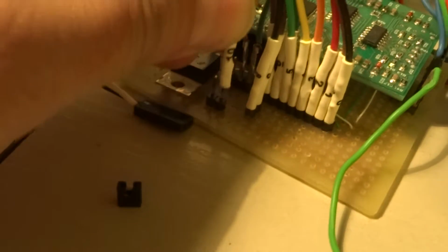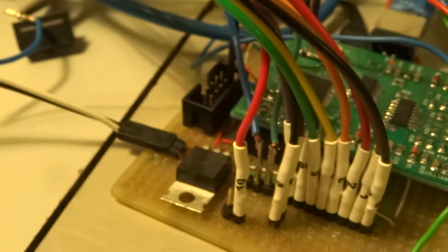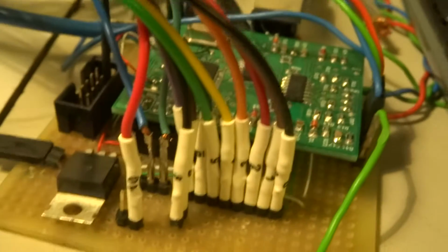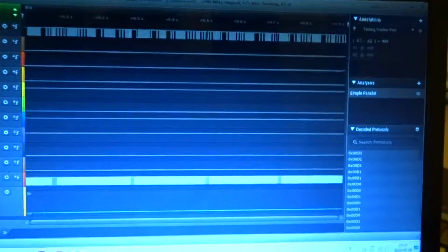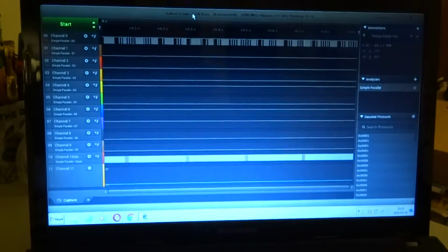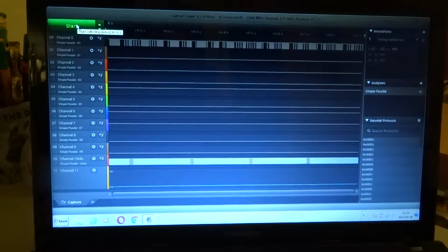and we go back to our sensor, disconnect mode. We connect the clock signal and we connect the supply. And here we have 10 digital lines connected directly to the serial logic analyzer, and we follow the cable, and we go back to the application which supports the serial logic analyzer. And what we do now, we start the trigger.